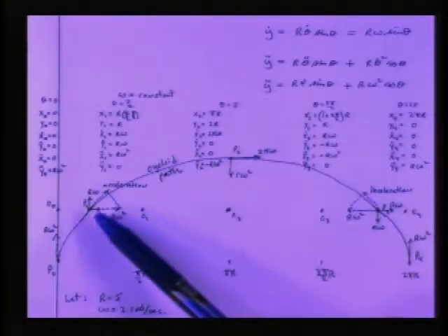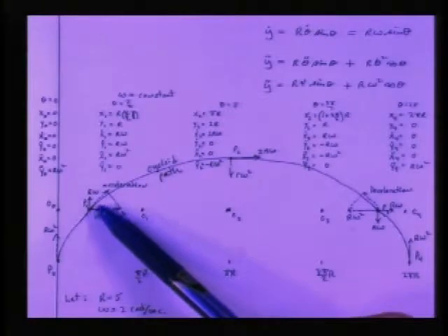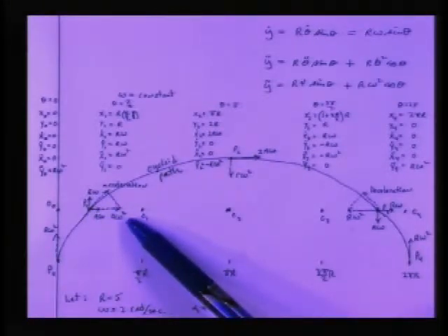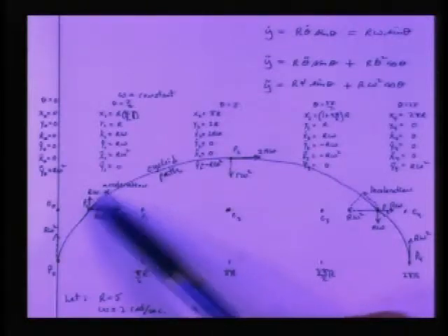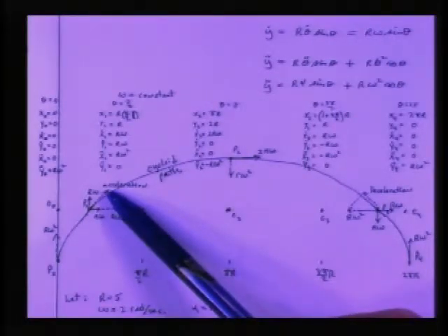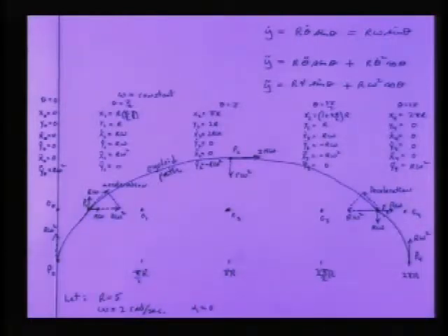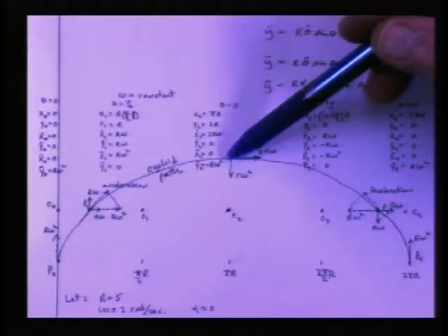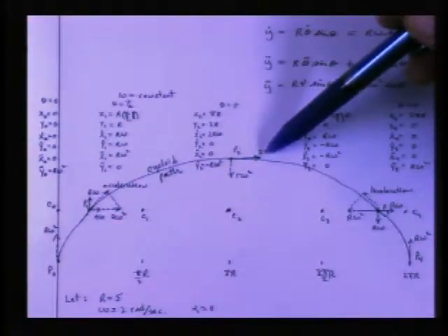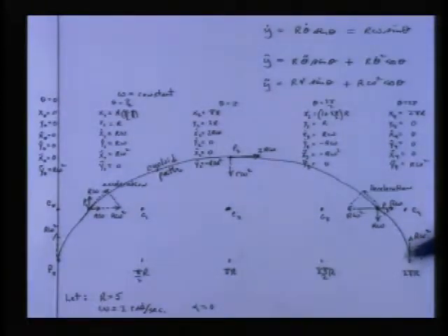Conversely, as that point is rising on the cycloid, here's the acceleration at the height of the center of the wheel. You can see that the component of the acceleration is along the direction of the velocity, so it's accelerating right there. Acceleration, deceleration. So it slows down as it's coming across the top. Remember last session we talked about the speed at the very top of its rotation being twice the speed of the wheel moving forward, and it slows down till it comes in with zero velocity down here, and then it lifts off again, comes back up.